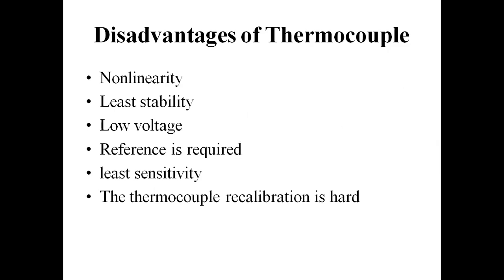What about the disadvantages of thermocouple? It has non-linearity, least stability, low voltage. The reference will be required, it will have least sensitivity. The thermocouple recalibration is a hard one.